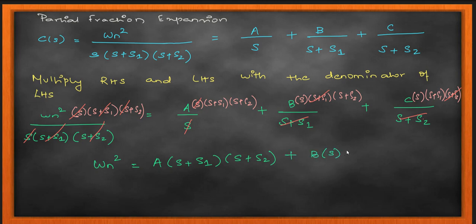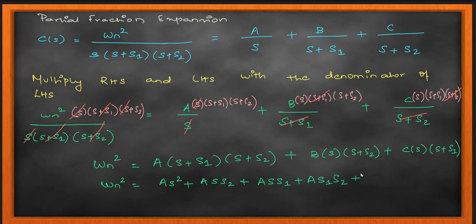In this case, for an overdamped system, your roots are occupying the real axis, and they can be on the right side of the real plane, or on the left side. On the real axis, the imaginary axis is in the center, right? So it's not a system that we are very fond of in our designs, where the roots occupy just a straight line in your S-plane, right?